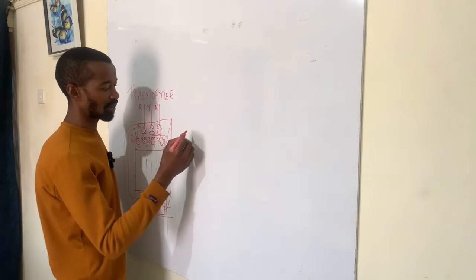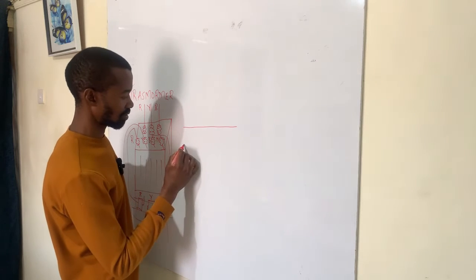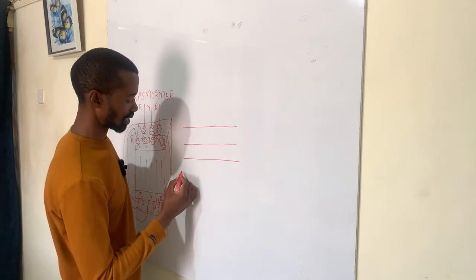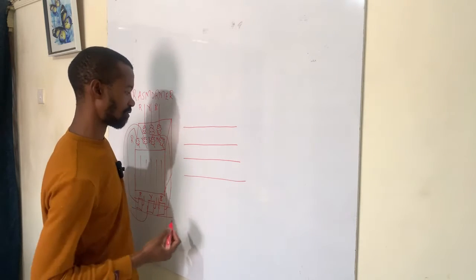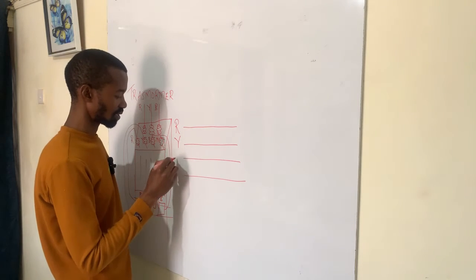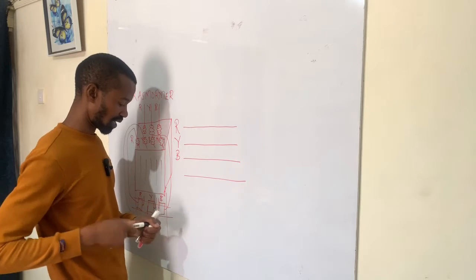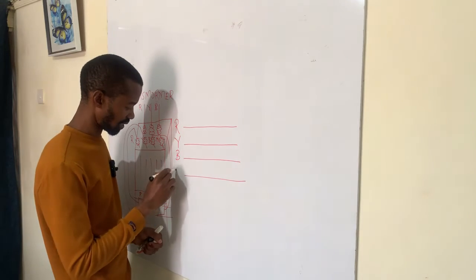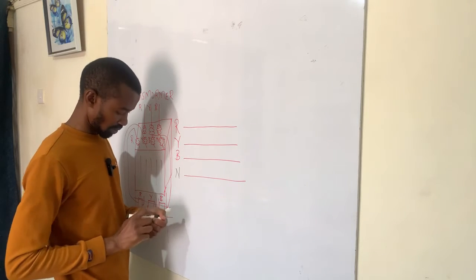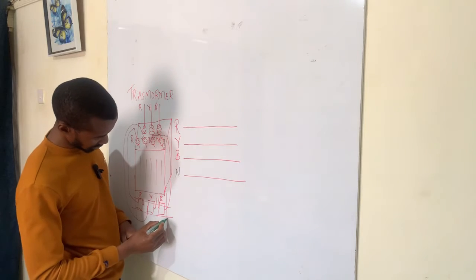Now, at the primary windings, we will have those conductors there that come from the transformer. Of course, the red phase, the yellow phase, the blue phase, and finally we'll have a neutral or the return. Of course, again, there is an earthing connection that is done at our transformer.